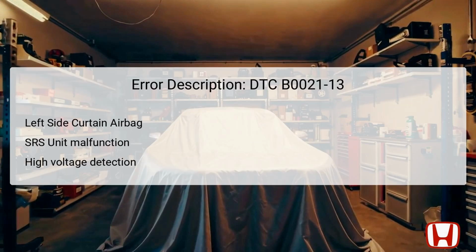DTC B0021-13 specifically indicates an issue with the left side curtain airbag's first inflator, which is integral to the SRS, or Supplemental Restraint System, of the Honda Accord. The SRS unit monitors various safety components, including airbags, and can store a DTC if it detects a condition where the voltage on the detection line is unusually high. This issue may arise if there is a wiring fault or open circuit affecting the airbag's inflator signal.